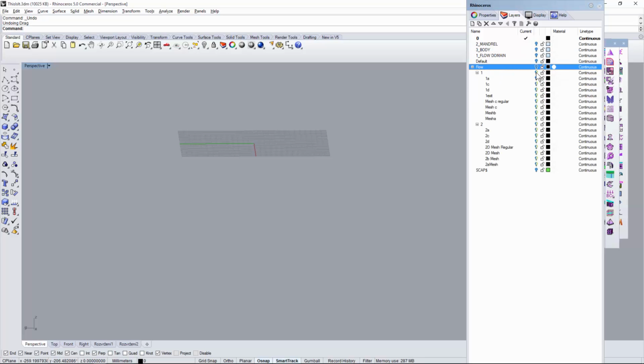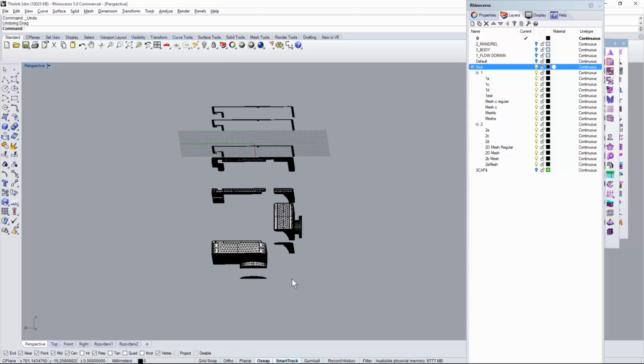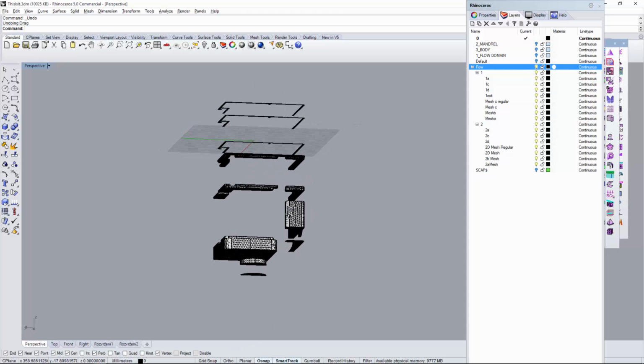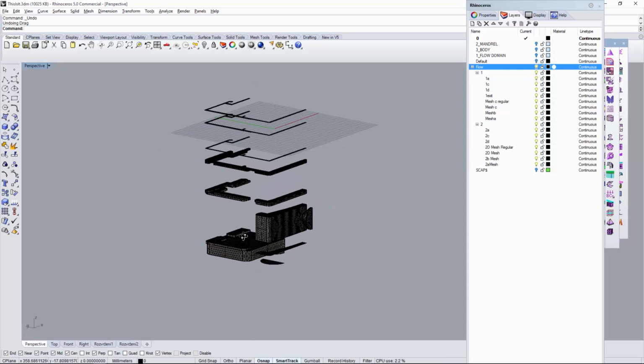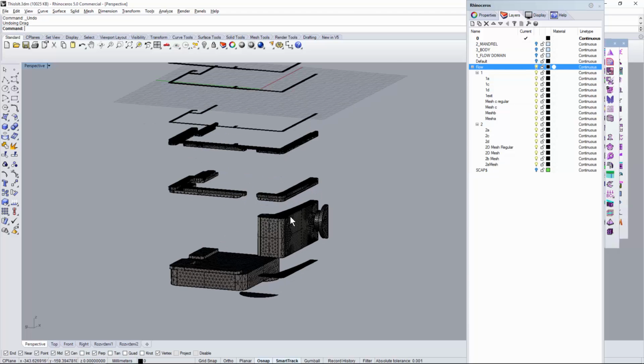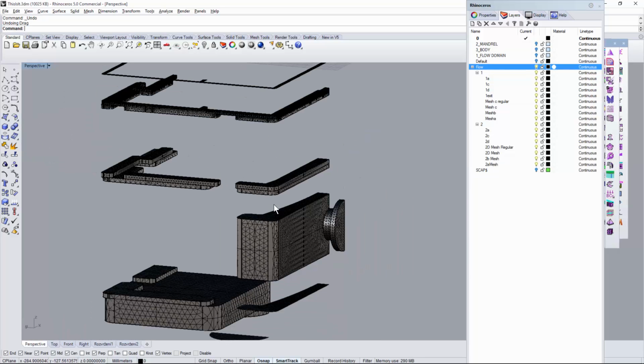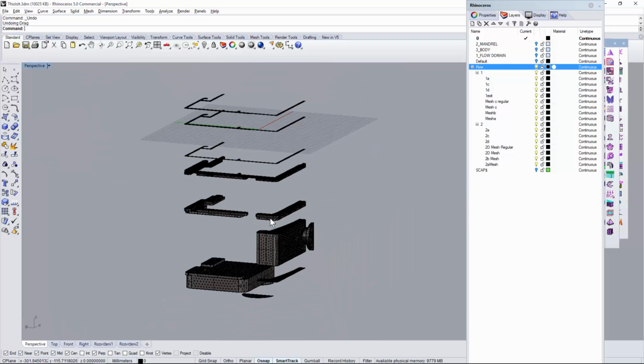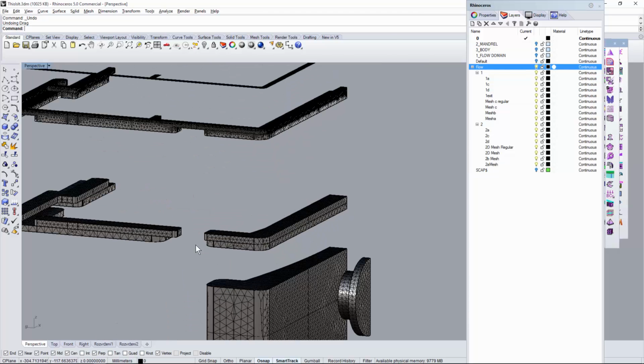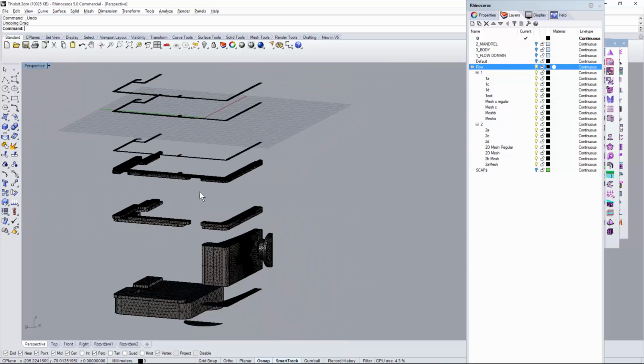We were doing the mesh like this. It was split into segments, you see, and only these particular segments were meshed. Why? Because there is a straight connection between these sections, so we don't need to mesh them, right? We need to mesh by automatic mesher only these narrow sections.